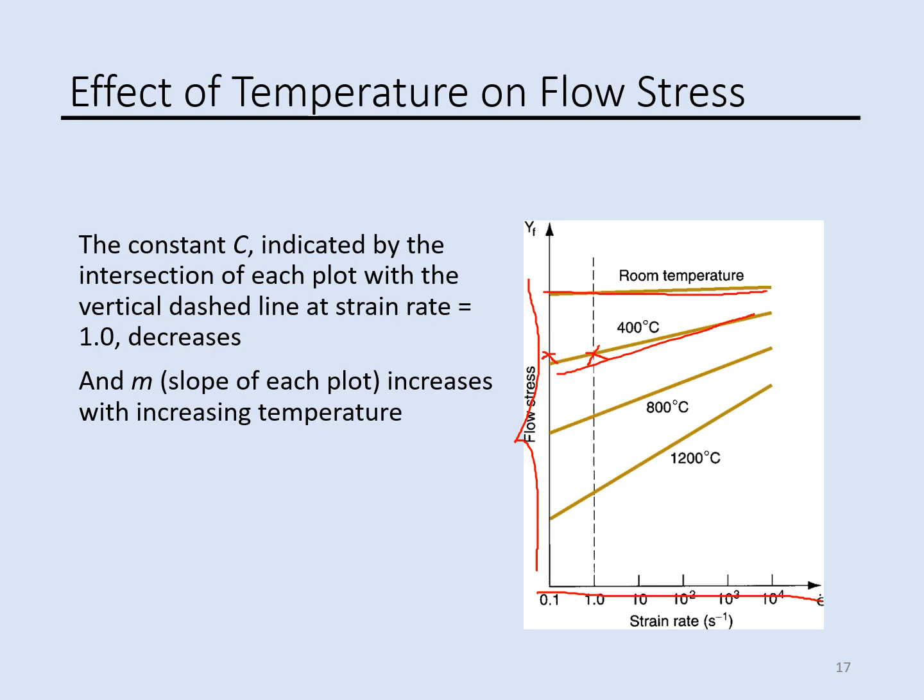But if you increase the strain rate, you go, for example, to 100. This is 100. So the flow stress goes up. So it is important to calculate the strain rate to find the respective flow stress for that application.